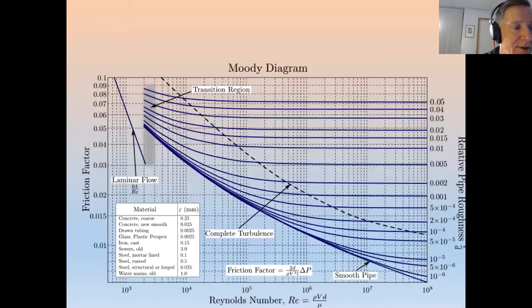And this is friction drag. It's kind of a scary graph to get started with, but we'll look at friction and pressure drag. Friction drag is the easiest one to understand. It's resistance to flow based on surface finish. I'm just going to look at this for a moment. On the left here, you see friction factor. On the right, Reynolds number, which is basically velocity. We'll look at that more later.